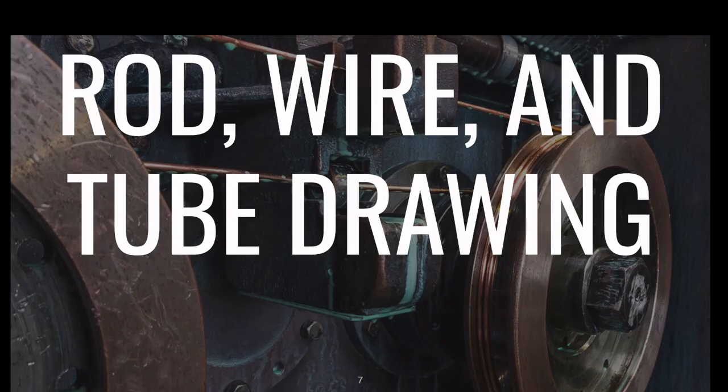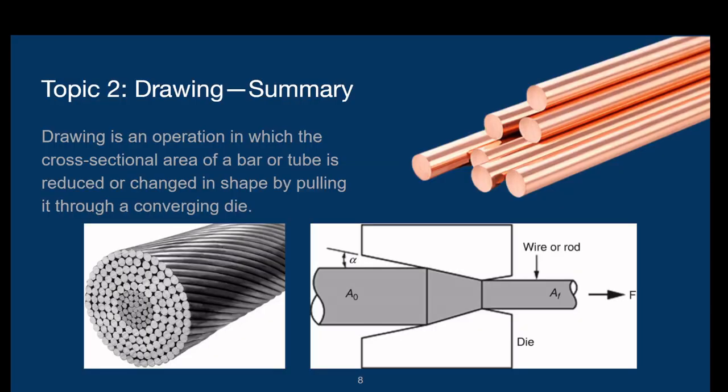The next topic I selected is rod, wire, and tube drawing, also known as just drawing for short. Drawing is an operation in which the cross-sectional area of a bar or tube is reduced and changed in shape by pulling it through a converging die. In some cases, multiple dies are used to draw out the material progressively. You can think of the drawing process as very similar to extrusion, except that the workpiece is under tension instead of compression.